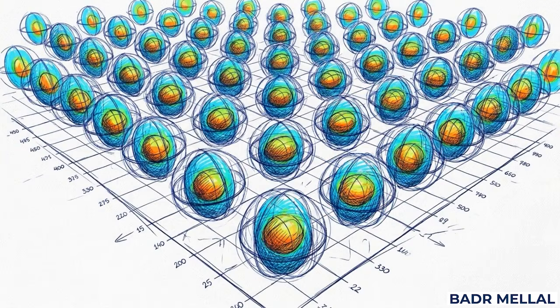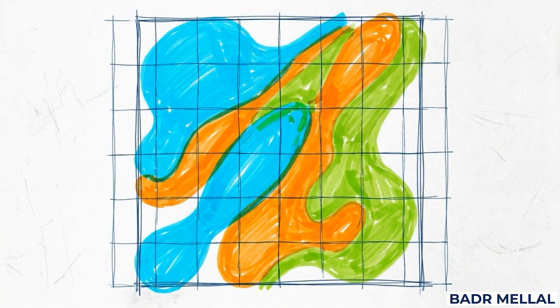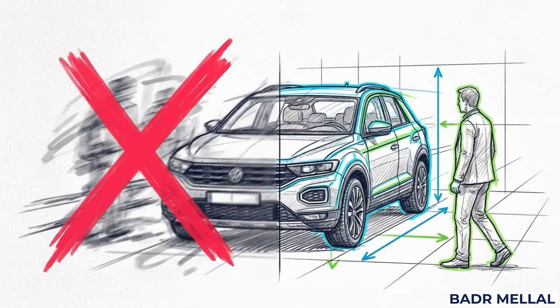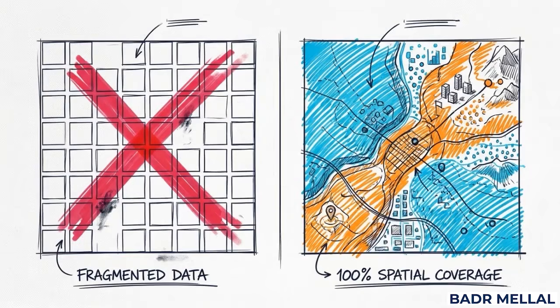By utilizing these continuous parameters, the architecture can deploy Gaussian splatting rasterization. It renders features directly onto the BEV grid, completely bypassing the slow, discrete sum pooling step. Treating the world as a series of continuous probability distributions inherently prevents the depth ambiguity of backward methods, while mathematically eliminating the sparsity of forward methods.